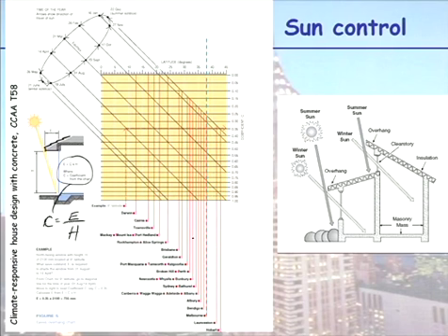Depending on where you are in the world, Darwin is a lot higher up. If it's closer to the equator, the sun is higher up in the sky. The further you are from the equator, the lower the sun is in the sky. So it's very important you realise where you are in the world as well as how big an awning you require. In this case, we've got Melbourne here, which I've dashed in with this blue line.